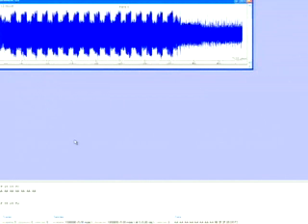So this is always the same input without any countermeasure. If you scroll through these, you'll see that there's almost no difference. They line up nicely. So also here the sidechannel attack works really well. I didn't do it live because it takes a little more measurements, like 20,000, but it works.